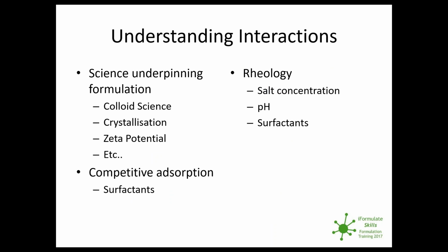So what is the science that underpins what you're doing in the formulation? Is it colloidal science? Is it crystallization? Do you need to understand a little bit about zeta potential? Maybe you might not think so in liquid blends, but you might be doing a suspension. If you've got a whole bunch of surfactants in your blend or in your product, then there's competitive adsorption onto solids, or they can actually interact with one another, and you need to understand what's going on there. And quite often you have rheology. Rheology can be influenced by many things, and it can be an effect of the salt, the pH, or the surfactant, or indeed a combination of them all.